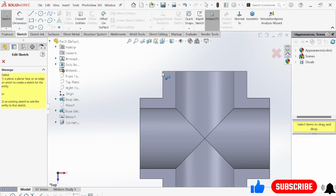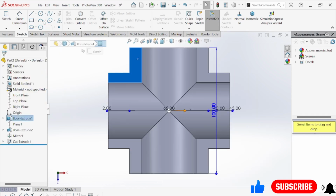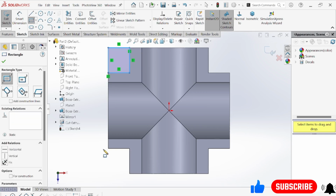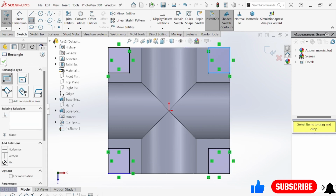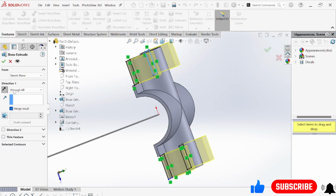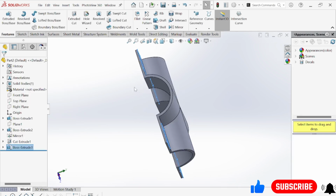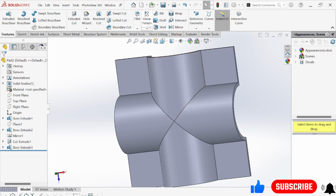Go to corner rectangle, select this surface, make sketch, go to corner rectangle, make a rectangle here like this, make one rectangle here like this, make one another, and one more. And go to feature, go to extruded boss base, through all. Now here you see this is our part. Now we need to make some fillets here.